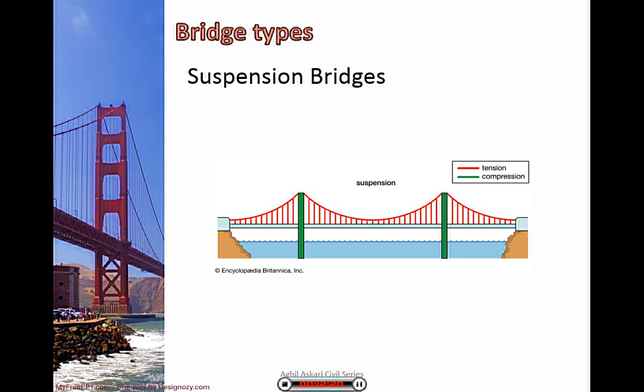It will depend upon the size of the bridge, but a number of towers will be installed to hold up the suspension cables. Any load applied to the bridge is transformed into tension across the suspension cables, which are the integral part of the structure. As there is some give in the suspension cables, this can translate into slight but measured bridge movement in difficult weather conditions.